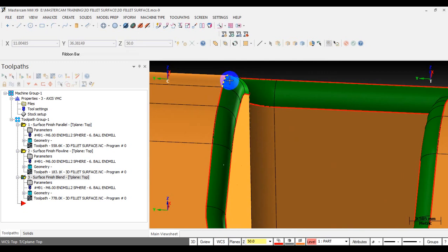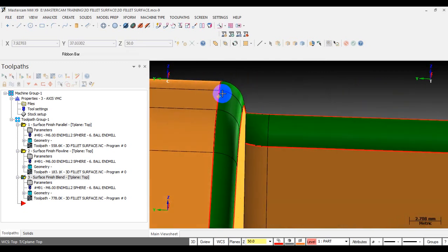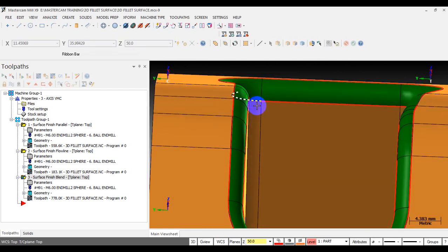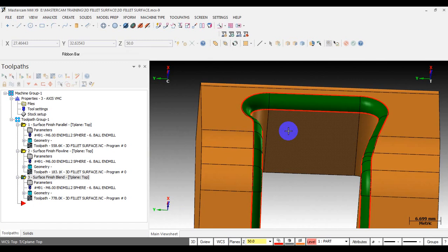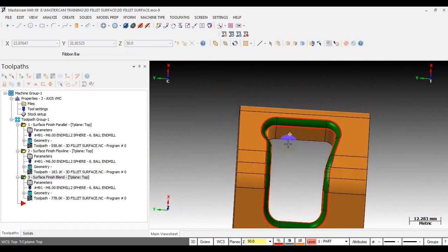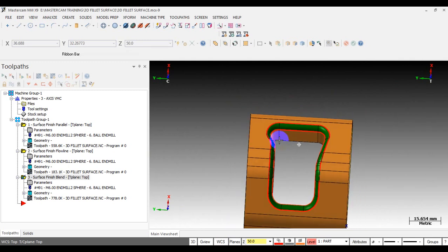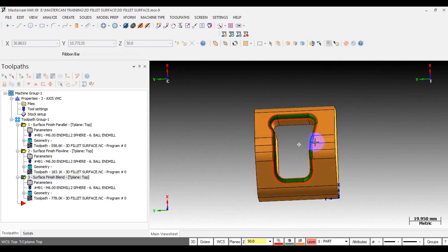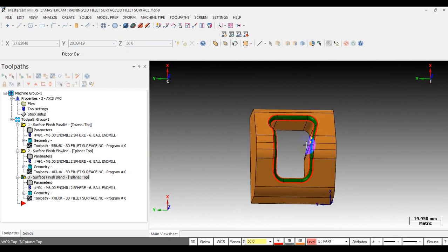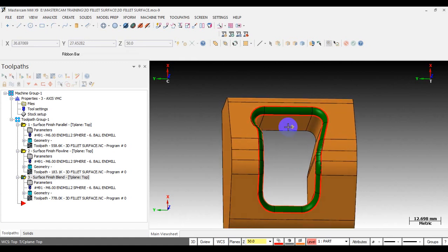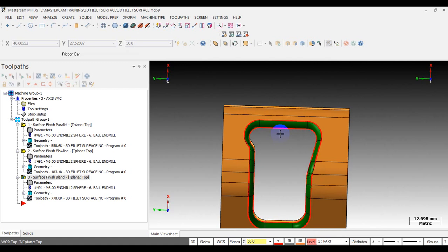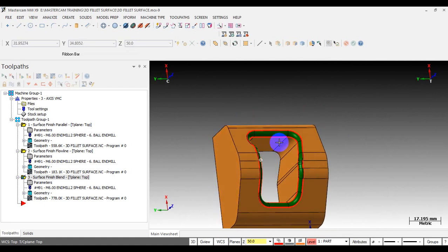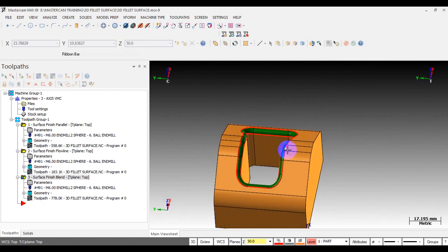In this area, this is shallow surface, so we don't need to modify this outer curve. But the problem is this inner curve, you need to extend it in the inside so the tool center can move further. So our trick for the plane toolpath is we have to move the inner chain, the chain in the steep area, far away from the surface so the tool have the space to go in. So I cannot use this chain. I will show you how to do this trick.